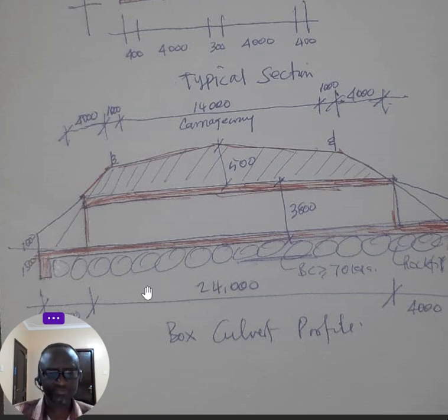So normally this cutoff beam, I personally also consider at least some scouring. You know, there are eddy currents at the flow, inlet and outlet of the culvert. That's why normally you see that the wing will start getting scoured, not actually at the front, because of these eddy currents and if there's any obstruction downstream and also at the upstream flow.